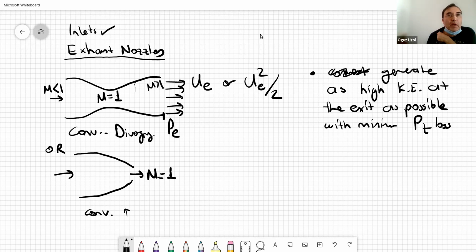That's the best condition because we don't have shock waves and we don't lose any total pressure. Okay, that's the design condition. That was not the case for intake, if you remember. In the intake that we discussed, the pitot type intake we discussed on Tuesday, it does have a converging diverging geometry, yes. But we do need a normal shock wave in that inlet. We cannot live without a shock wave because that shock wave is the only mechanism to reduce to subsonic speeds. That's at the intake, we need low subsonic in the compressor. So that shock wave has to stay there. But in the nozzle, there shouldn't be any shock waves under design operation. Do you understand this point?